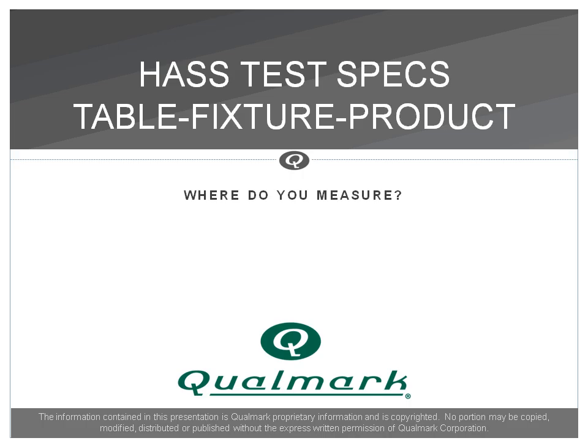And I put this in just as an example to understand why we say over and over again, you've got to monitor on the product when you're looking at thermal and vibration. If you think about it for a minute, if your failure modes are happening on the sub-assemblies inside of a product, on boards or other components, and you have a housing around that, that housing, the structure that is around the sub-assemblies, is a big mechanical filter and will change the vibration characteristics on the product itself.